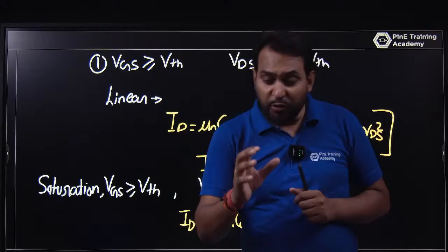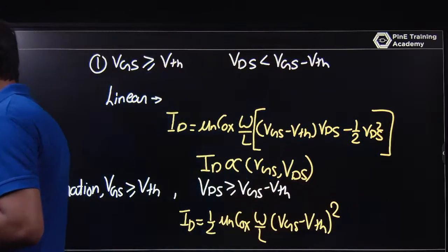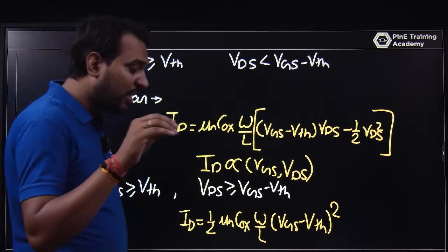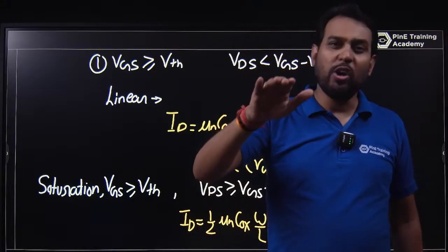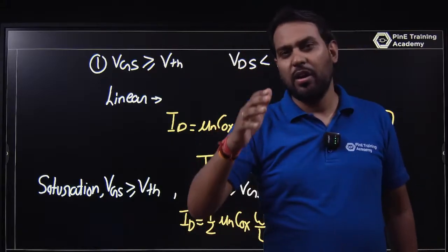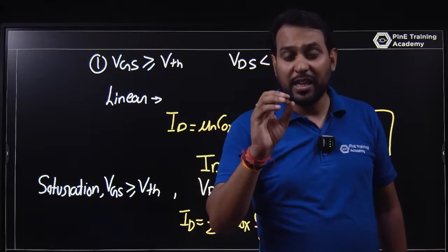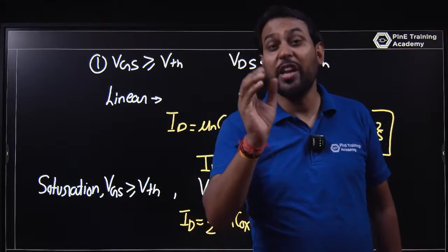Okay, so if you are designing with 180 nanometer, 90 nanometer, or 55, 65 nanometer, the sub-threshold conduction current ID is very small. But as you go to lower technology, like 22 nanometer, you will find that the sub-threshold conduction value is very high. That current is very high.